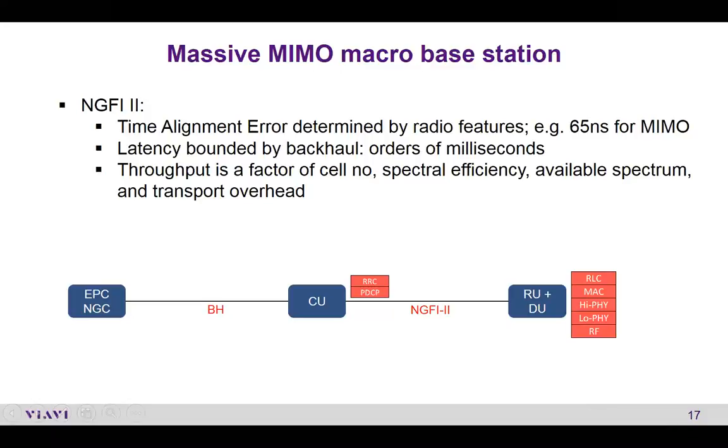If you're looking at performing a time alignment error or time error measurement, then as some of our audience knows, to perform that you would need a good reference signal. If you have a GPS used at your radio, then you would also need a reference with access to a GPS, and then you would be able to perform time error measurement.